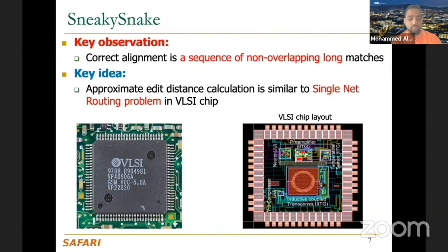Now, shortest path or lowest cost has multiple definitions. It could be the lowest latency, the minimum energy consumption, or the least routing cost, for example, because for these routing paths you pay a cost, right? And you don't want to increase their number, because they're going to increase the energy or take space, because they will collide with those modules. So your goal is to find the shortest path from one point to another point while connecting some of these components or avoiding these components. It depends on your design schema. So that is the single net routing problem.